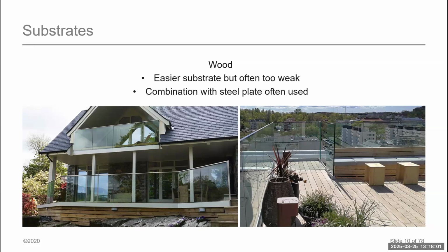So what we need to be cognizant of is when we do wood, we either need to have a steel angle behind it, where we can fasten through it into the steel angle, or what we need to take into consideration is we need to offer wood blocking, where we're going to have attachment points for guardrails when we're using a wood substrate.